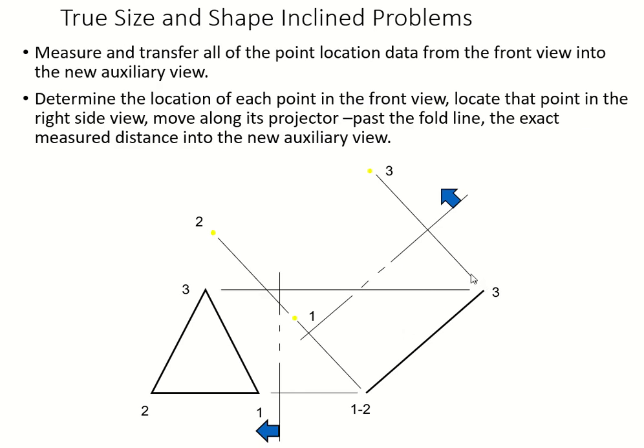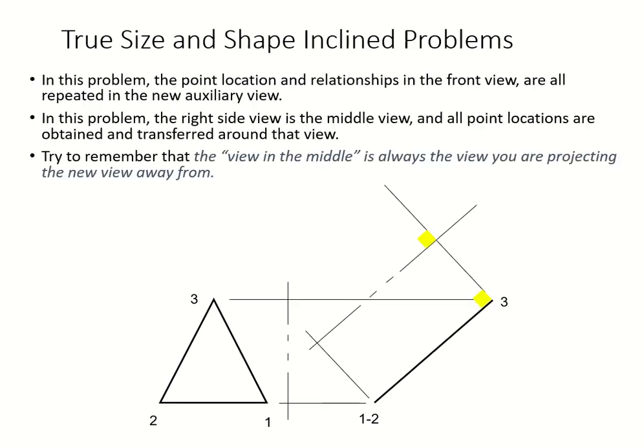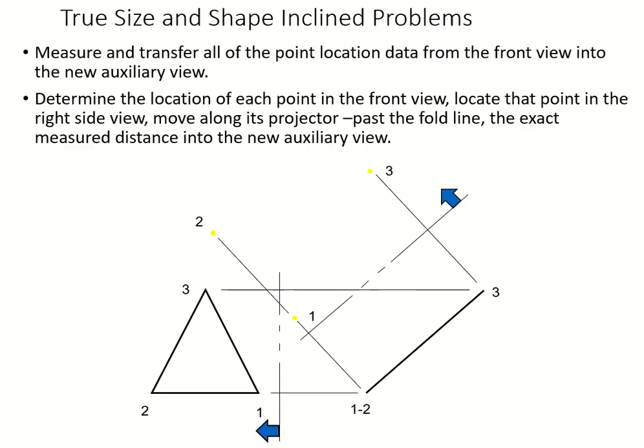We do the same thing. Here is your projector. So we're going to move it, extend it all the way up. So this arrow is just showing you, please extend. Let's go back to the previous slide so you can see. So this was before, and now we're extending out. Since this is a right view, we have 2 points going on. So the very first point is number 1. So we're going to start with the 1. And you're going to extend, how much do you have to extend past this full line? You're going to extend the same distance. So from here to here, you already have your measure, and then you're going to stop it.